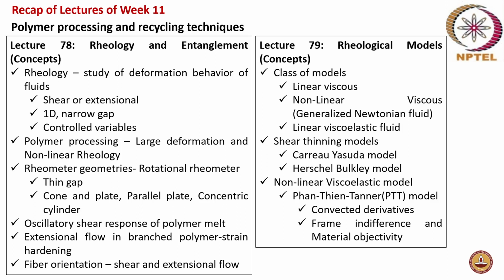Here the discussion was on shear flow, extensional flow, and how, using rheometers, you can make the flow one-dimensional with narrow gaps and control many variables, so that you can understand the flow behavior elaborately. In polymer processing you will have large deformation and non-linear rheology, whereas during the viscoelastic behavior discussion we studied small deformation and mostly covered linear rheology. So non-linear rheology becomes a critical factor in polymer processing and in understanding material behavior subjected to large deformation.